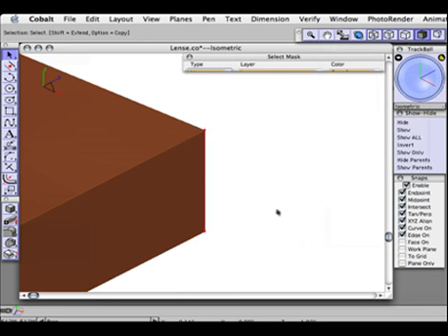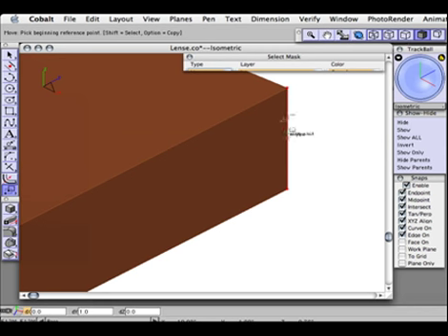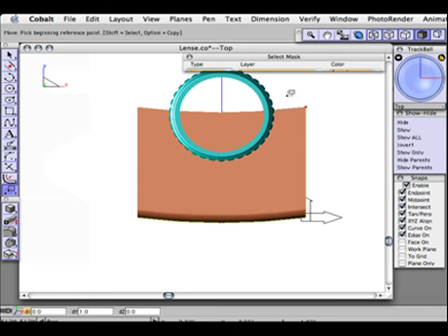I'm going to drag a selection around two endpoints and the one line. And where I could just click and drag to pull these lines over, I'm going to use the Move tool and click one point, come out the Y direction and click again. And notice I'm actually just editing wireframe geometry here, but because that wireframe has history, the solid updates as a result. Type in a value of 1, and now notice that this part extends past the center.